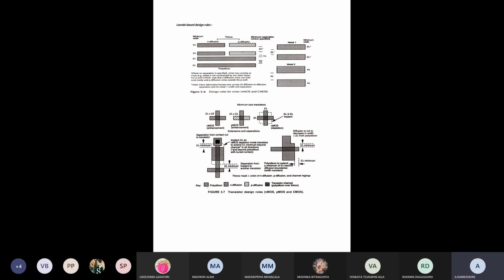If you have the possibility, practice from the Pucknell book. In the Pucknell book, you have to see the layout diagrams and the stick diagrams. First take a Boolean expression, and from that expression design a transistor diagram. After that, draw a stick diagram, and then a stick diagram with colors. You have to practice with colors, so that you can draw very effectively in the examination.